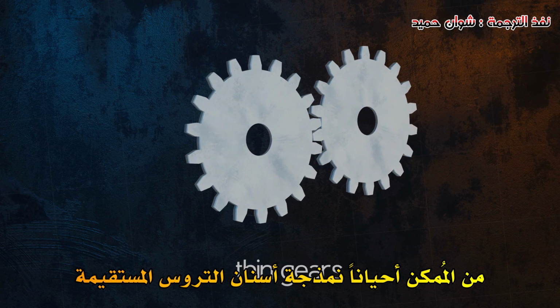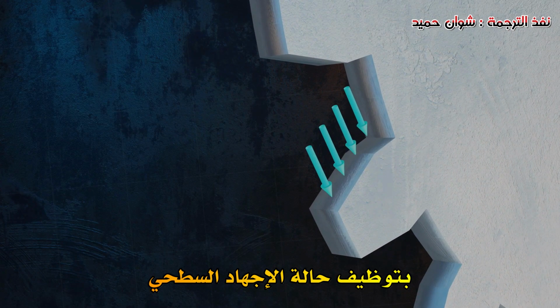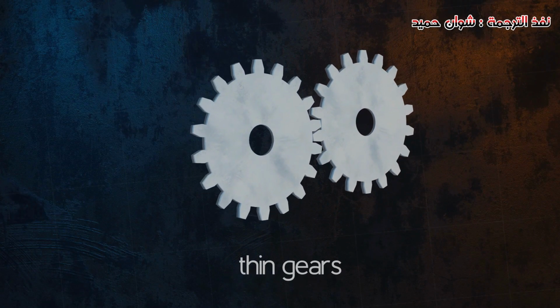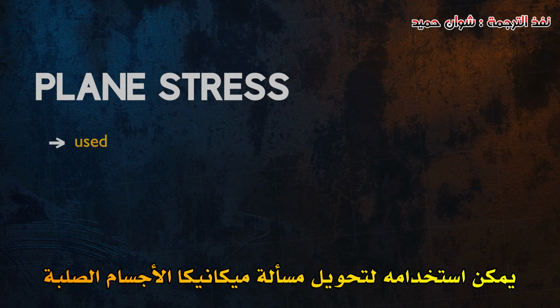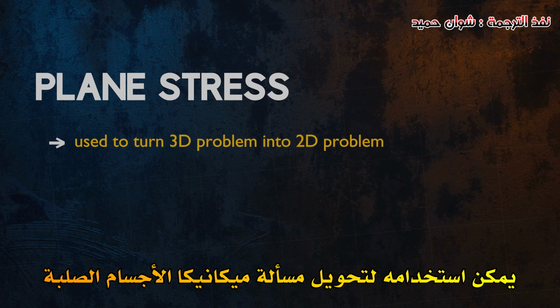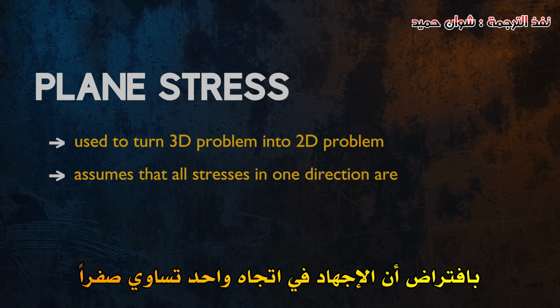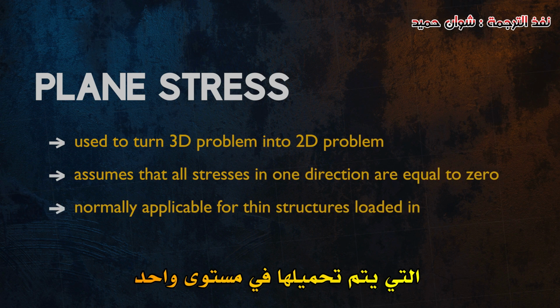The teeth of a spur gear can also sometimes be modeled using plane stress conditions, if the width of the gear is narrow enough. So, to summarize, plane stress is a simplification which can be used to turn a 3-dimensional solid mechanics problem into a simpler 2-dimensional one by assuming that the stresses in one direction are equal to 0. It is normally applicable for thin structures which are loaded in a single plane.